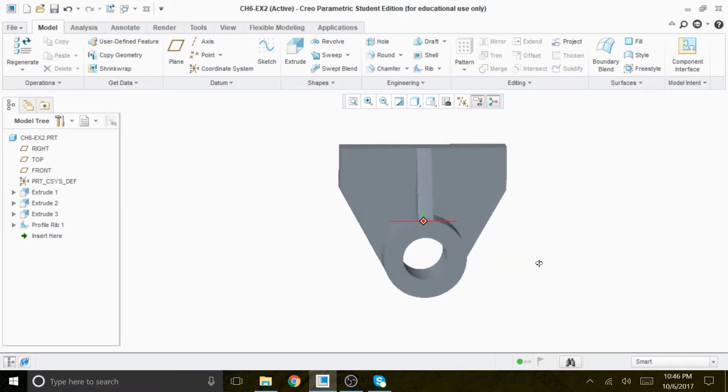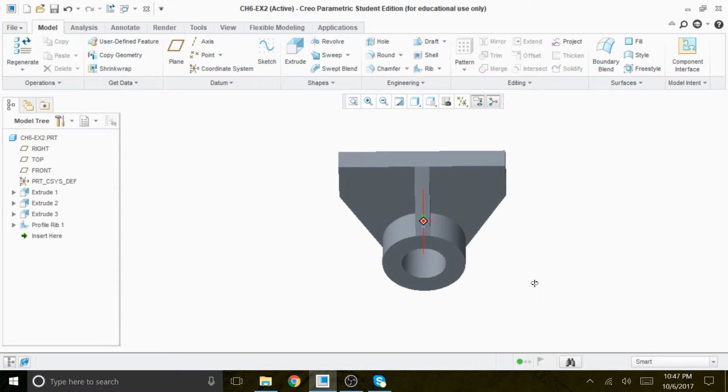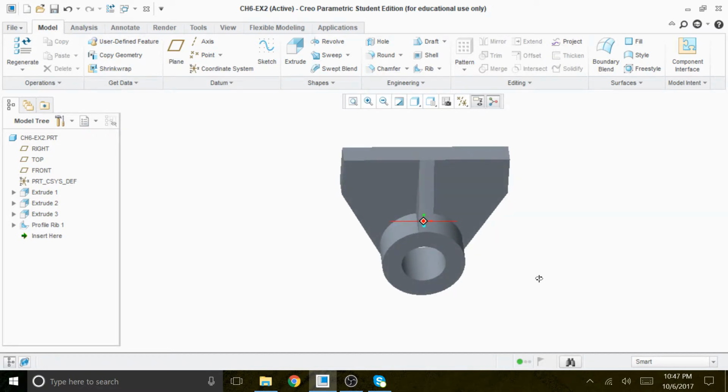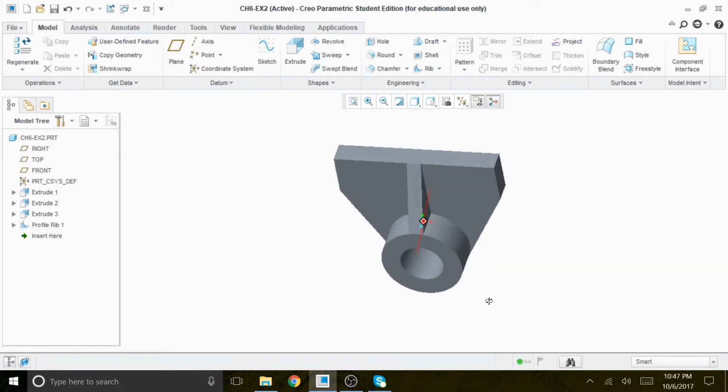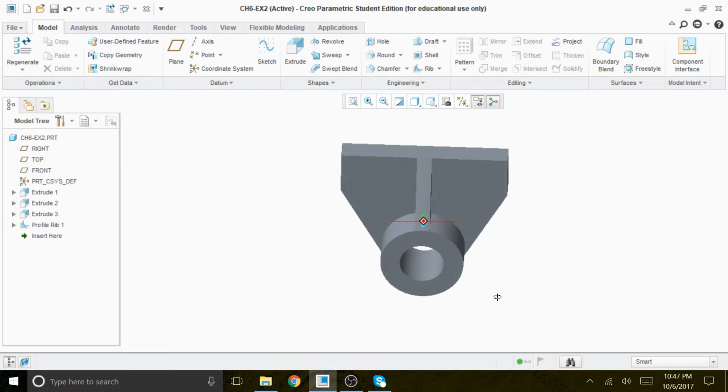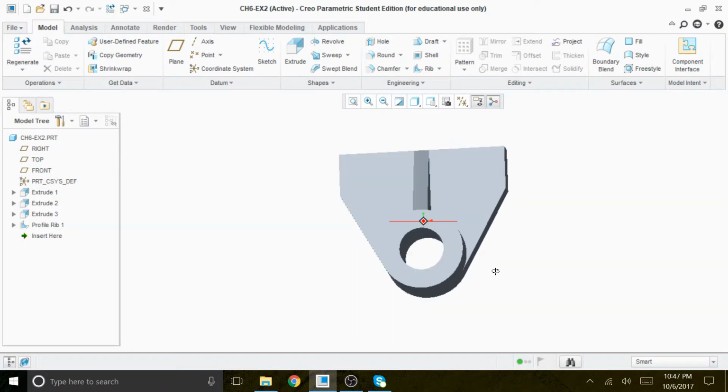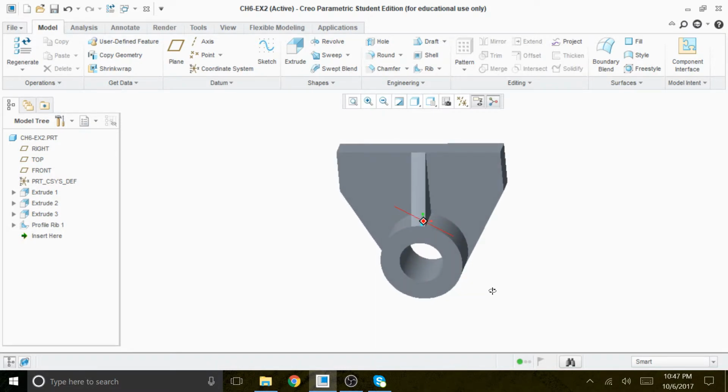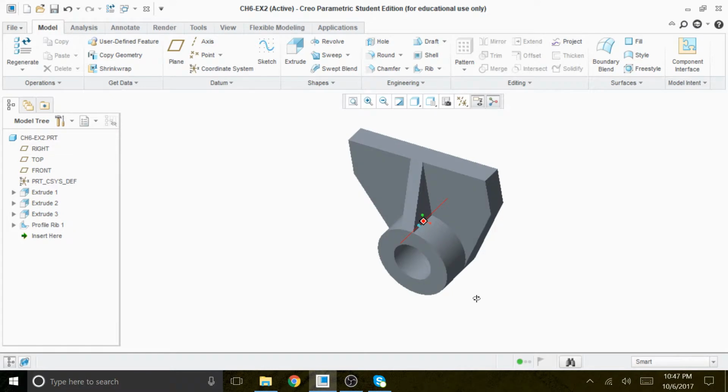When we create the blueprints or 2D layout, you will see what we're talking about, the 3 views. Some people like to use the left side view, which in most cases has fewer invisible lines than visible lines. The recommendation is to pick the 2 or 3 views needed to show the shape of an object with maximum clarity. Maximum clarity.